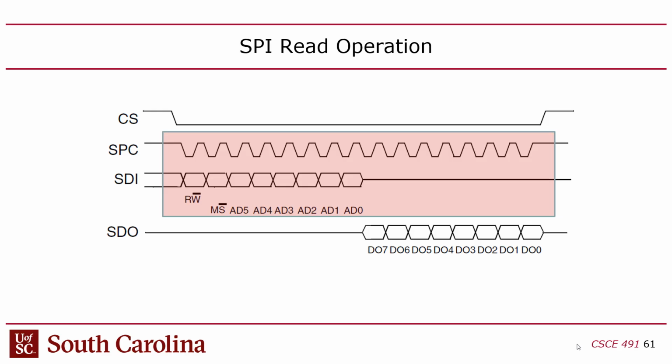Now, again, if you only have 64 registers, that memory is going to be small enough that the latency should be small as well. The smaller the memory, the smaller the latency, right? It shouldn't take a lot of time. But it would be nice if there could be a back pressure mechanism where the slave could say, okay, I'll do it, but you've got to give me a few cycles, I'll get back to you on this data. No way to do that in SPI, okay?